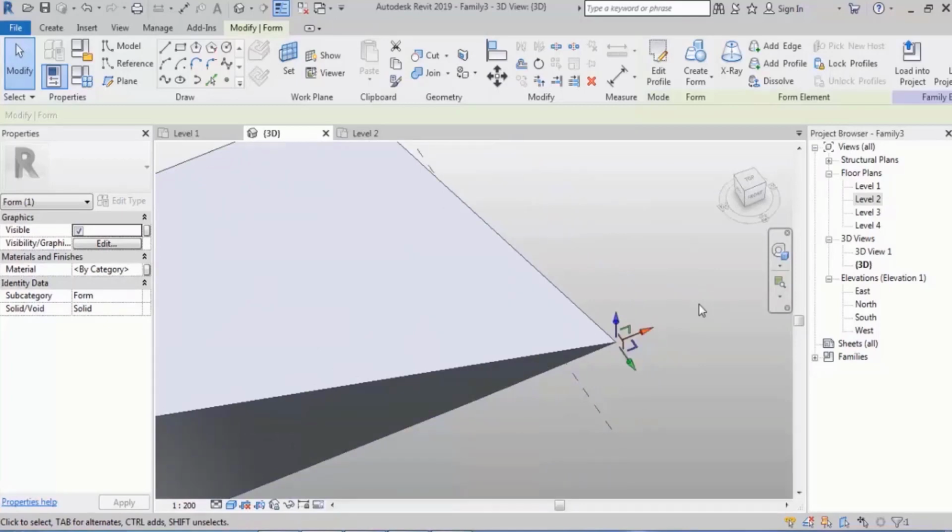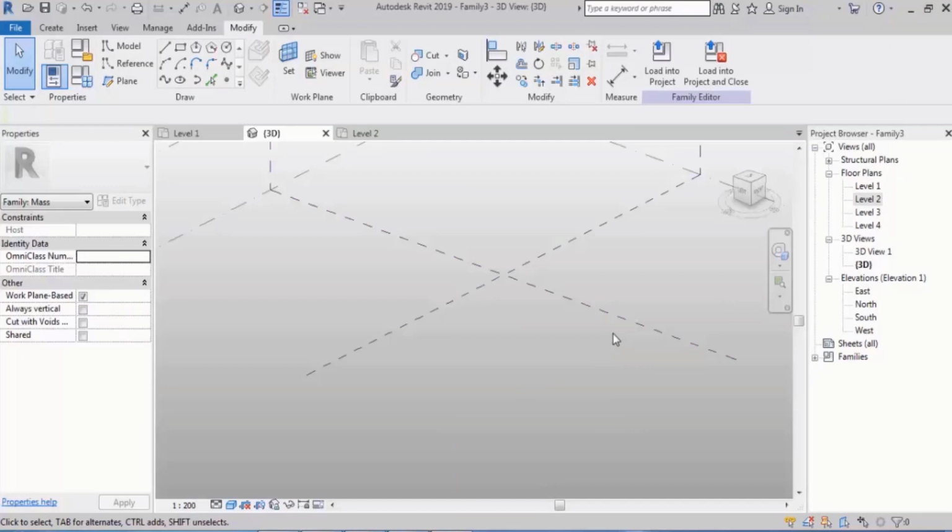Now, as you see, when I click on space, both of them will be switched to global directions. Sometimes it's in local directions, and we will face it later and talk about it. So, as you see, for moving vertex, edge, and surface, we use these arrows, right?